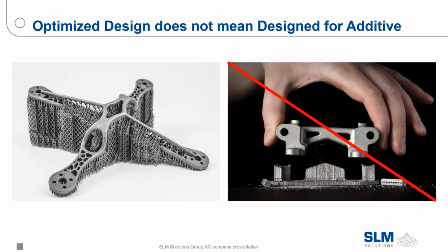Design, will it work? Metal powder bed has a couple unique challenges as far as supporting, mitigating stress from the welding process, and preventing voids that would otherwise trap unwelded powder. If we're looking to replace a subassembly that may have a completely closed chamber, we won't be able to produce that in metal additive because of our process. That chamber would be full of powder, so we're going to have to design a way to remove that powder from this system.